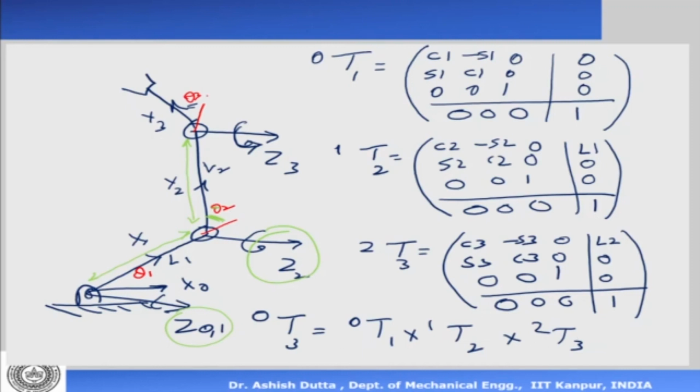So suppose theta 3 changes, just for explaining. If theta 3 changes, what will happen is this end effector will come here, and that will be taken care of by this matrix. So the rotation takes place here, right? If theta 2 changes, then the rotation will take place in the corresponding matrix. So you can see that each of these has a variable which is theta 1, theta 2, and theta 3. So when I multiply them out, this is what I get. So next thing we need to do is to multiply this out. So let's multiply it out.